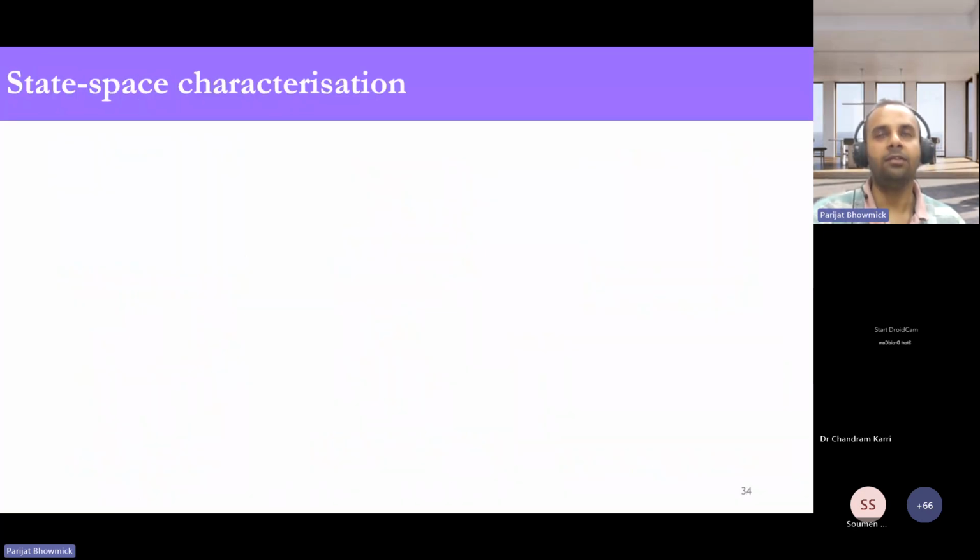So now I will ask you a question about what we have understood so far. There is this SISO definition, right? If you deal with a SISO LTI system, SISO means single input, single output, a scalar system, you have these graphical tools available. Given a SISO system, you can easily check the polar plot by using MATLAB or any other kind of software, and easily detect the property. You can conclude whether it's an NI system at all, or whether it's even an SNI.